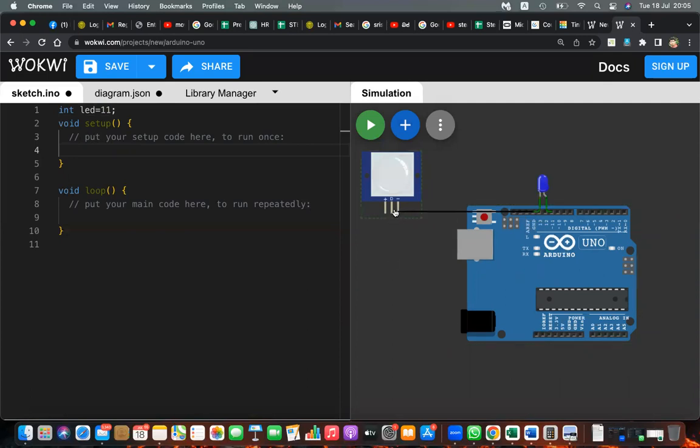Yeah, it shows where I need to connect. VCC I can connect here, 3.3 volt or 5 volt, we'll connect to 5 volt. Then this one I can connect to any pin which can accept. I'm connected to pin number 7, right?